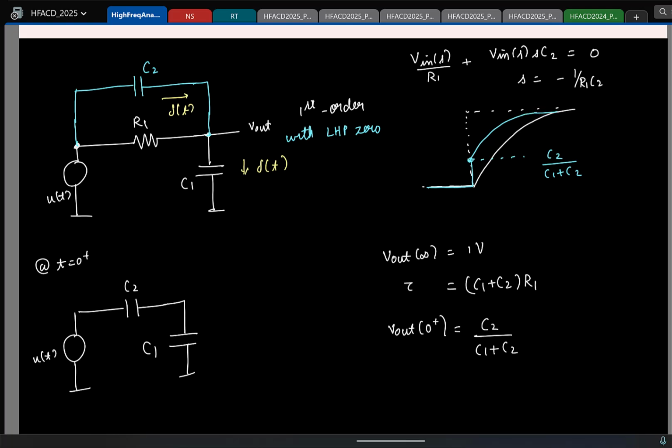Okay. So this is how an LHP 0 introduces time advance. Which means if you already had a lot of poles in your network, you would have incurred a lot of time delay. Now introducing an LHP 0 will have a time advance, reducing the effective delay in the system, making it more and more stable. Is that logic fine? So that's what happens. I'll just mark it here. I'll have an LHP 0. I'll just say that it counters the time delay due to poles.